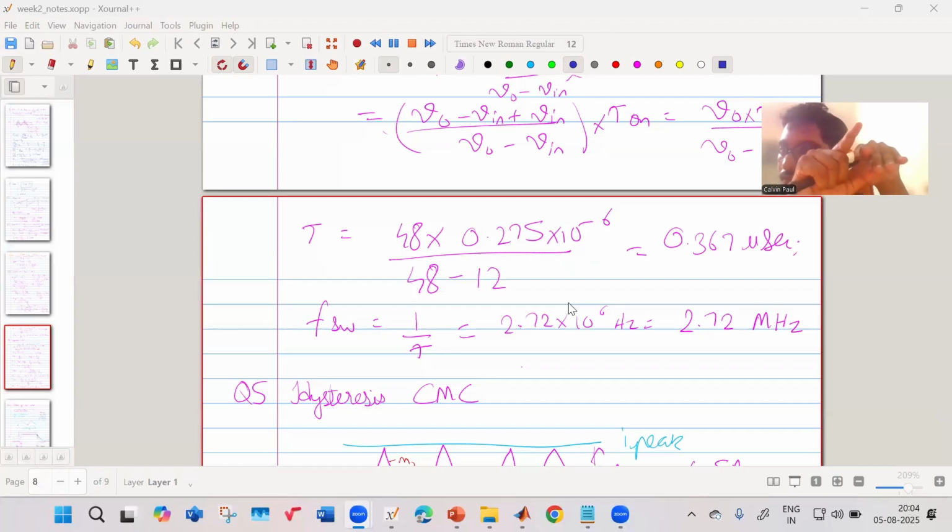Now, all this, your reverse recovery, the switch capacitor charging and discharging, and soft switching, where the switch node voltage rings to zero and then you turn on ZVS. All these things are very difficult to do in this way. It's not impossible, but it is difficult. It will be time consuming. Your MATLAB simulation also will run for a lot of time. So it's not recommended to use MATLAB for those things.